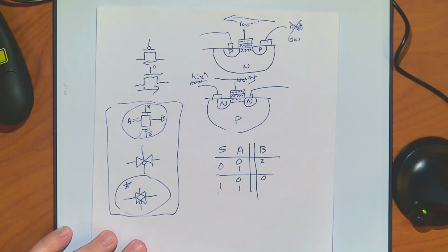Right? Now, that's not ideal because sometimes there's ways you might have both the signal and its inverse already there, and so you save space if you don't put the inverter in. Right? And there are a lot of times we have both. So think, for instance, on a flip-flop, you have both available to you. So why get an inverter? Just grab it from its appropriate areas.